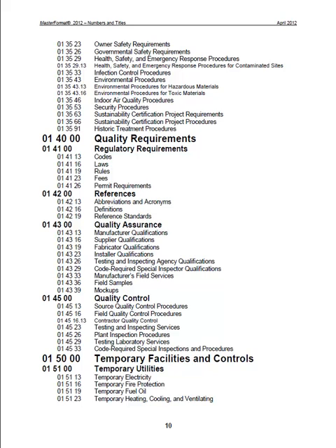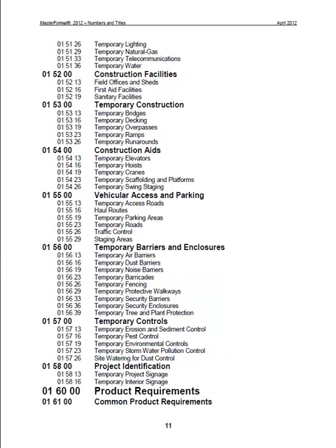a wall section in masonry. The engineer may require them to build a mock-up of that wall construction with masonry so that they can check the colors, make sure it looks right before it actually gets put into the building. And again, it's a good insurance policy to say, yes, that's what we want, or no, let's try something a little different. This doesn't really fit our needs. So occasionally we do ask for mock-ups on particular wall construction types to make sure that we're satisfied that it's going to do the job for us.